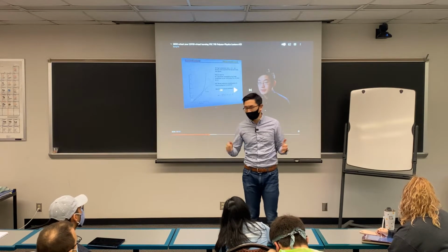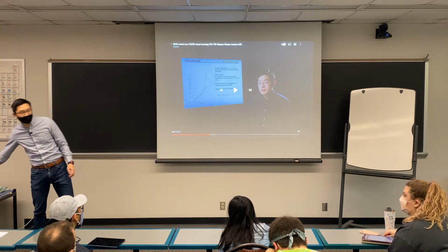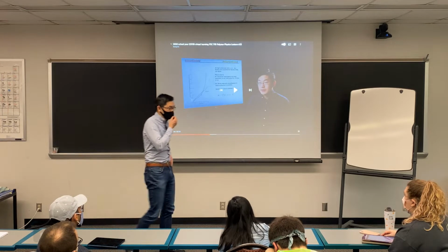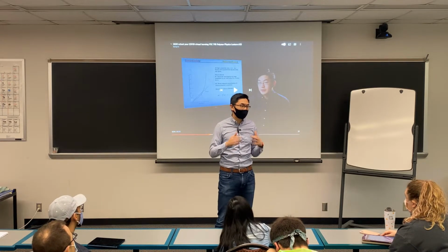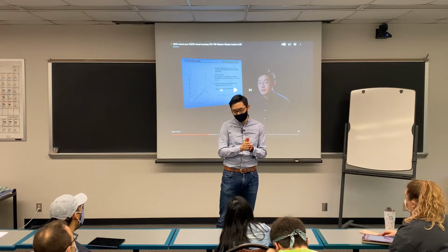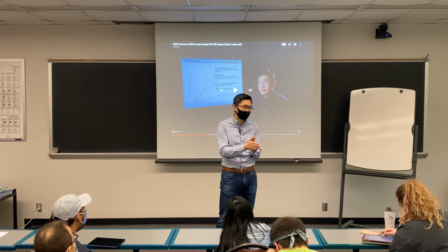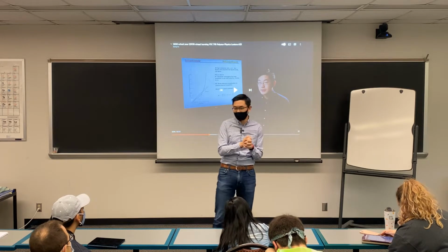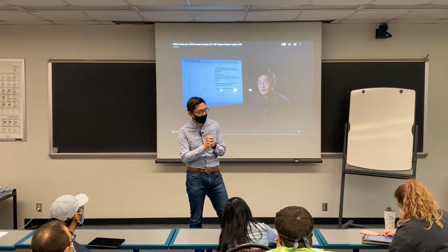And crystallization is a concept you probably haven't heard because it will be covered in the solid state property course next semester in greater detail. But briefly speaking, crystallization is when your chains are able to align in a perfect lattice. They will form something called a crystalline region. And that typically happens at low temperature, at the crystallization temperature, okay?